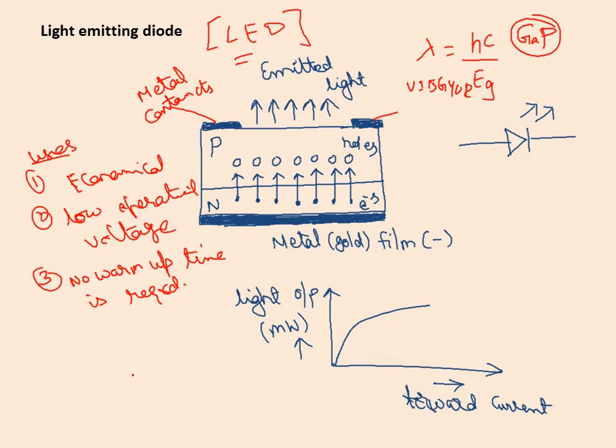The moment when they are switched on, you can notice that both of them will glow with increasing intensity. The light does not switch on fully at once. The moment you switch it on, you are not going to get the pure white light or the pure orange light. Did you notice this ever? That is what we call warm up time. For sodium vapor lamps and mercury vapor lamps, the warm up time is required.